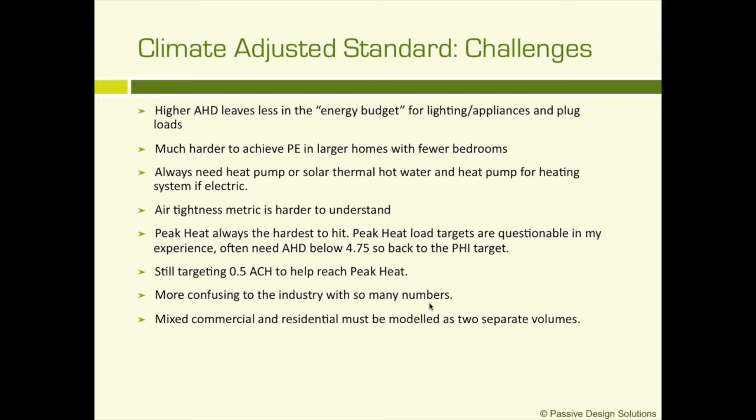And the peak load is really there to maintain comfort. So we're really back to the PHI target for the annual heat demand, which means more strategies that may not be cost effective in the building. So we're making an argument with PHIUS that the peak heat load targets may be set too high to be cost effective. And one of the strategies that we're using to help reach the peak heat load is